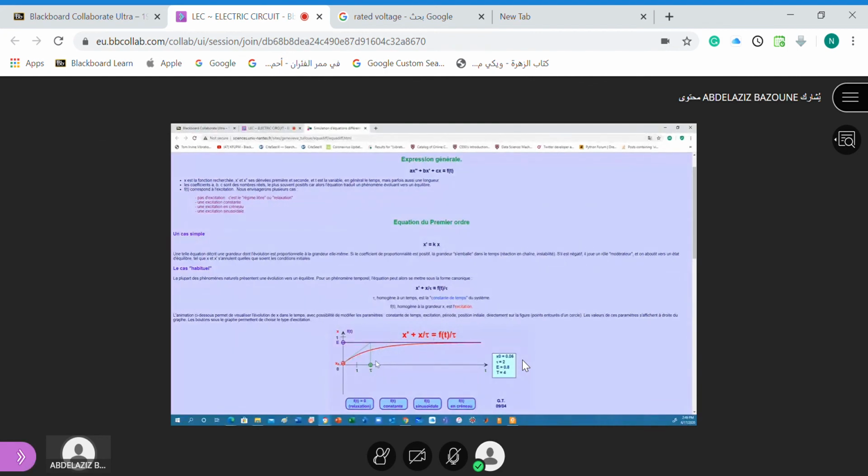Shabab, this is the step function. This is the E voltage, E here on the left-hand side, as you can see, and then the value is E. This is the initial condition. Our initial condition, now we put it at 0. And the red one is the behavior of the step response. For tau, you draw a tangent at the origin. It crosses the final line here, and this will give you the tau. So tau can be a measure of how fast the response will go to the steady state.